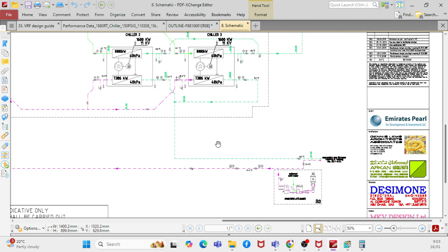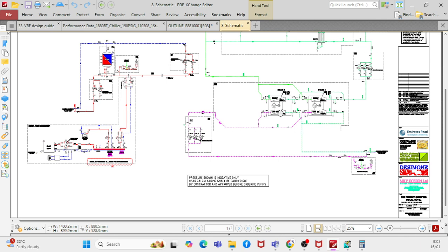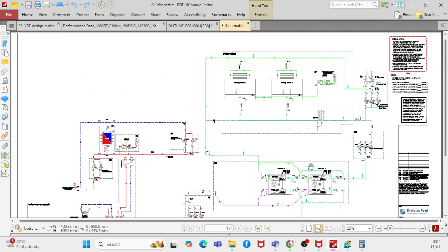But when you have a water cooled chiller, as we saw last time, there is a building side: you have a chiller, then a pump, a pressurization unit, and chemical treatment. Then you have an FHU, AHU or FCU, whatever it is. In a water cooled chiller, you have another circuit called the condenser water circuit: the chiller condenser side, then the cooling tower, then the condenser water pump, then water treatment.